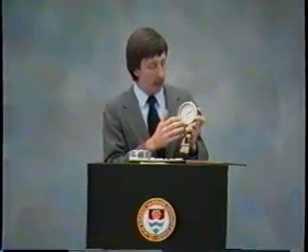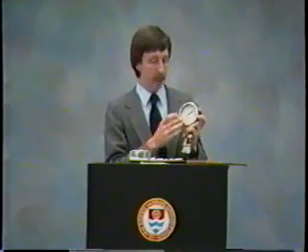Another design of a pitot gauge is this type, which can actually be clamped on the outlet of the hydrant. This has the advantage of having two scales in that it not only records the pressure equivalent to the velocity head, but also converts that reading into gallons per minute of flow. Now you have to be careful when you're doing this, because while the pressure readings are just velocity head, the gallon per minute readings